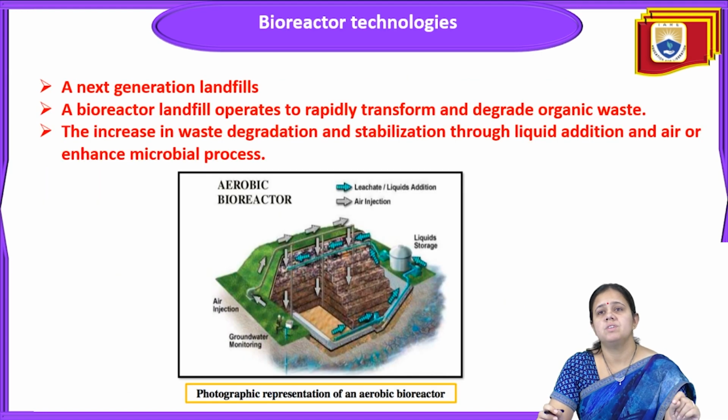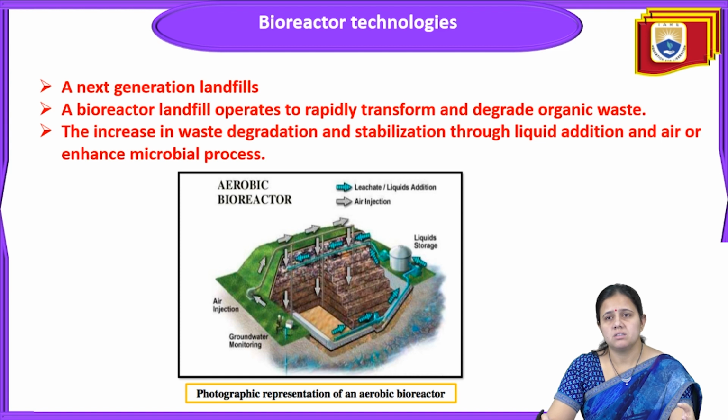We will discuss the technology, because nowadays in every big city, a landfill is there on the outskirts of the city, and leachate generation from the landfill is a very common problem. To sort out these problems, for the treatment of landfill leachate, two methods have been used, aerobic methods and anaerobic methods. For example, the activated sludge system, the trickling filter, or sometimes a leachate pond, which is called an aerated lagoon.